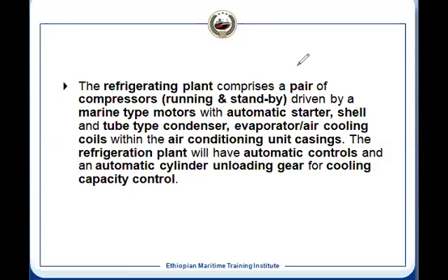Whereas in this type of heat exchanger, there is no thermal expansion provision. It means the tube plate is welded onto the shell, so both ends are fixed. So we are not actually allowing any differential thermal expansion. Our material design should be such that it expands equally, so there should be minimum differential expansion between the shell and the tube nest. And if there is no relative expansion, then there will not be any thermal stress because of the temperature difference. So it is kept in such a way.